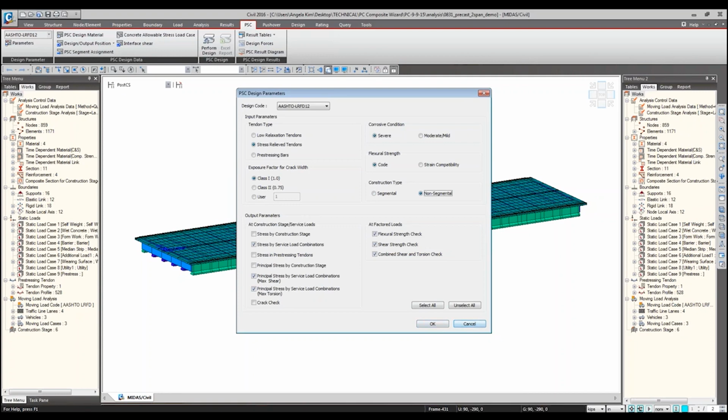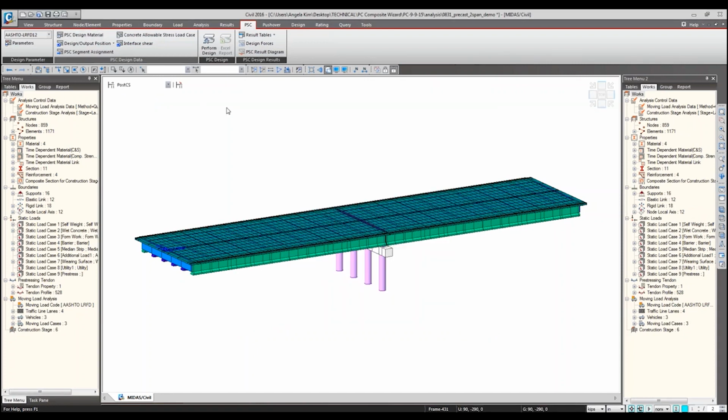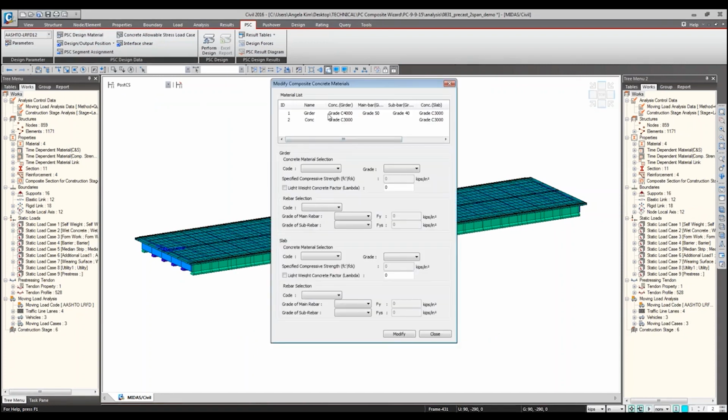So after you specify the design parameters according to AASHTO, you can also define the design material. This is where you can choose the material database, or if you need to make modifications to the strength, if your DOT has something special, not very general in AASHTO, you can always reset your database here and have access to modify the strength information of the material.